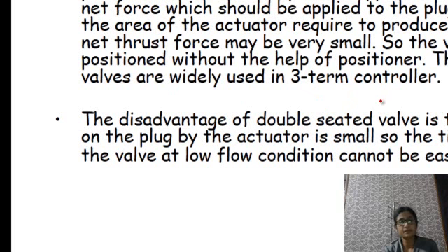Disadvantages of the double-seated valve: definitely it has a drawback. As it has two seat areas, the force applied on the plug by the actuator is small. So the tight shut-off condition of the valve at low flow condition cannot be easily obtained.